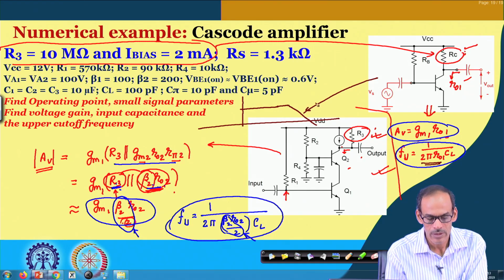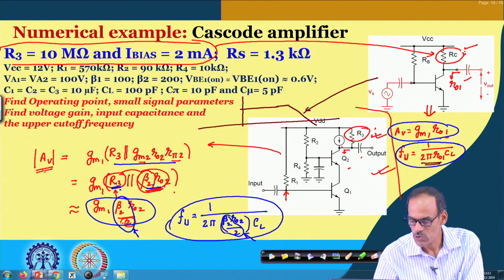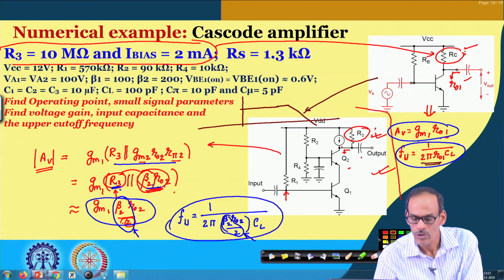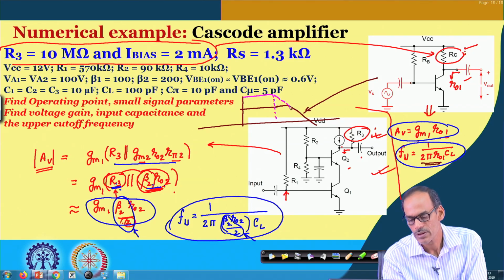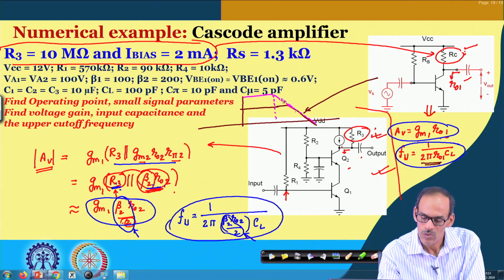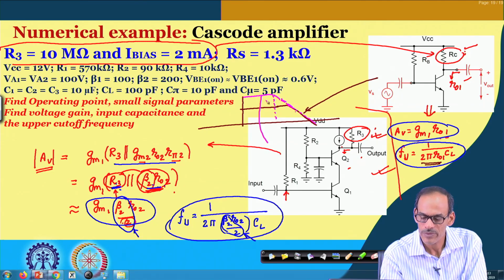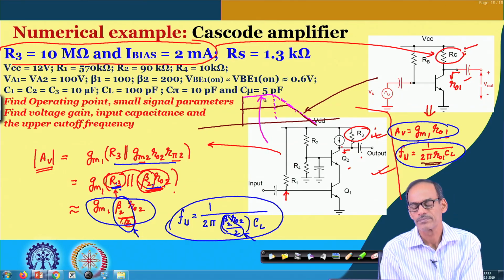On the other hand, if I consider the cascode amplifier, the gain is quite high and then the corresponding cutoff frequency is lower. But then if you see, the roll off here, they are finally coinciding. So, this pink color is the performance of the cascode amplifier.